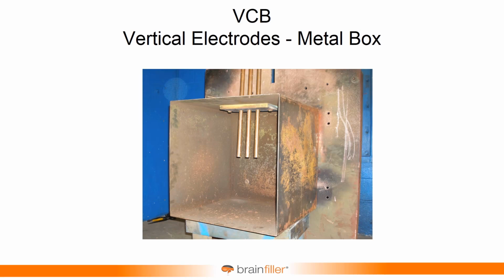You see the 3 electrodes, and you take a fuse wire, I call it a trigger wire, and wrap it around the electrodes, and that basically creates a short circuit. Then when you close the breaker into the short circuit, that wire vaporizes, and the arc is established. It runs away from the supply, and the energy comes off the tips. It goes down and then spills out of the box off of the end of the tips.